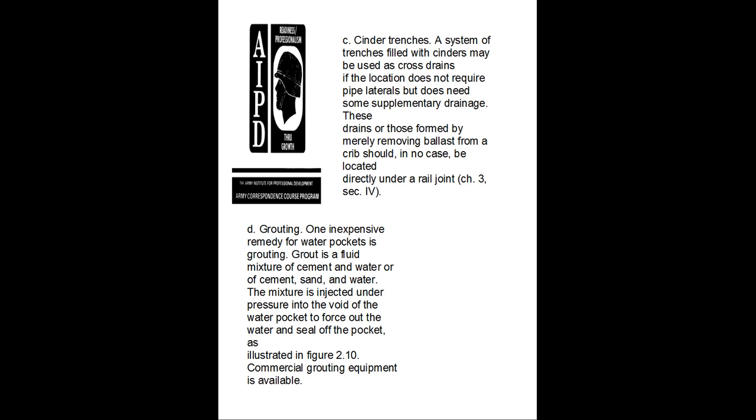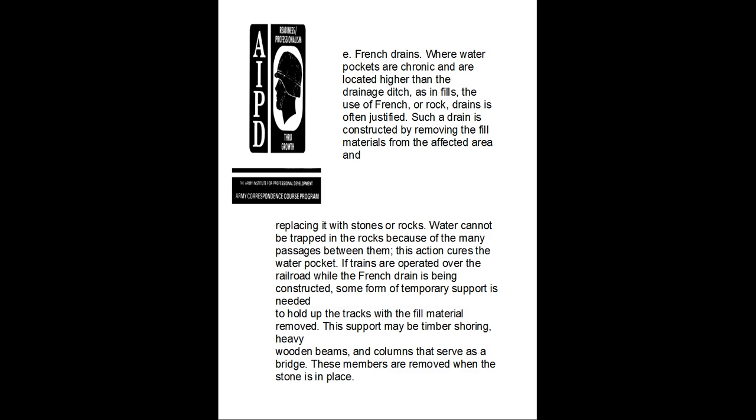D. Grouting. One effective remedy for water pockets is grouting. Grout is a fluid mixture of cement, sand, and water, injected under pressure into the void of the water pocket to force the water out and seal off the pocket, as illustrated in Figure 2-10. Commercial grouting equipment is available.